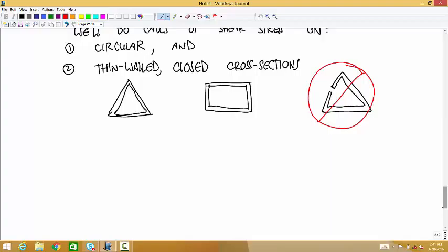And you can't figure out much near where the external loads are applied because of St. Venant's principle. The only way I can think of applying the right amount of newtons that you want, trying to model one of these, is with weight and gravity. But how do you apply newtons from the side? You could do it with some kind of threaded jack system or something.